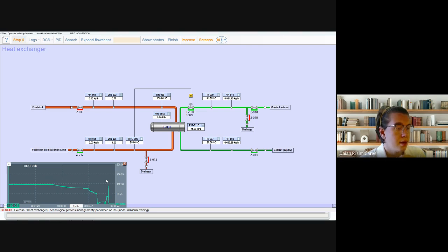We should understand that a heat exchanger is very expensive, and all facilities at the refinery are very expensive, so we have to work with them very carefully. We always start the device from the cooling circuit and turn it on from the hot circuit.